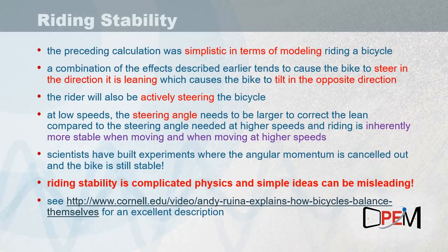And so in this case where you push a riderless bike and let it roll along, especially as it gets to lower speeds, but still not so slow that it becomes unstable, you can even detect this wobble back and forth of the bike starting to fall in one direction, the steering turning, and that causing it to then start leaning in the other direction. And it's this sort of self-correcting effect of the steering of the front wheel that's a key aspect of the inherent stability.